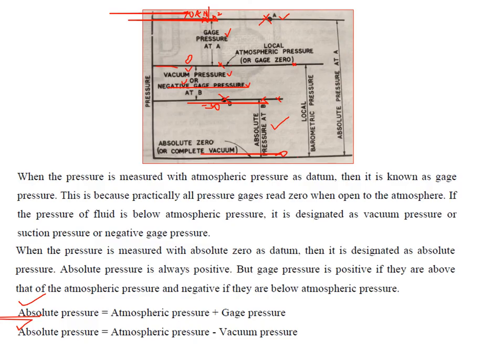Simple U-tube manometers are used to measure the pressure at a particular point. If you want to find the difference of pressure between any 2 points, then you have to connect a U-tube manometer to the 2 points. One limb is connected to one point, and the other limb is connected to the other point. Such a type is known as a differential manometer. But in simple U-tube manometers, only one point is connected to the pressure point, and the other limb is exposed to the atmosphere.